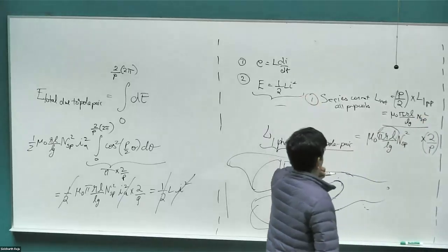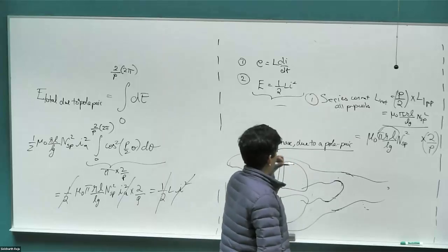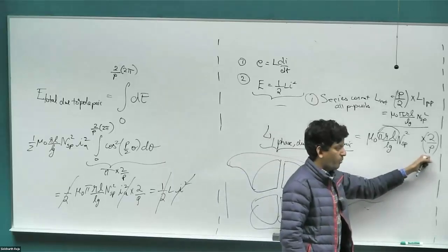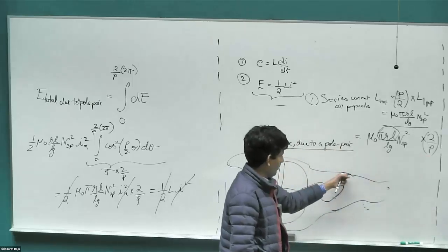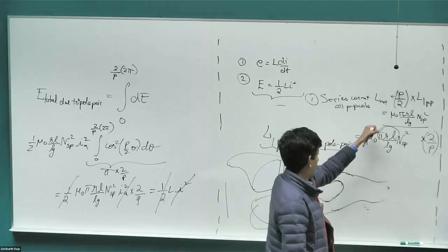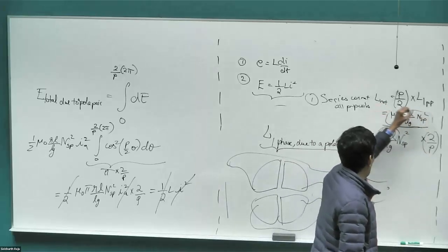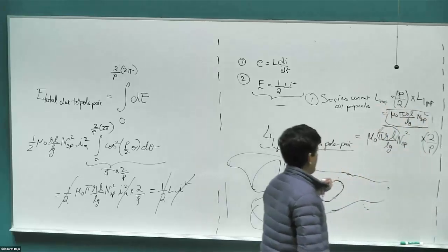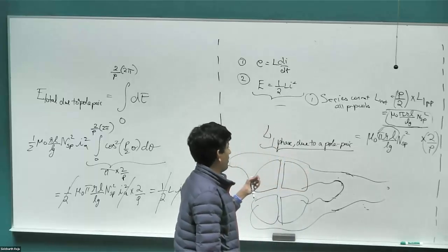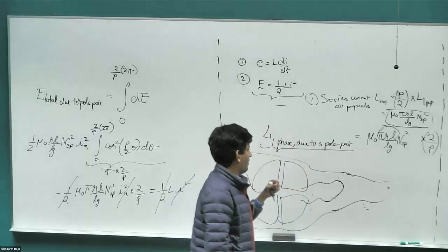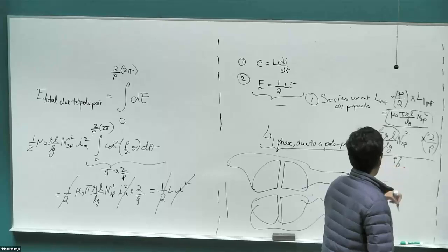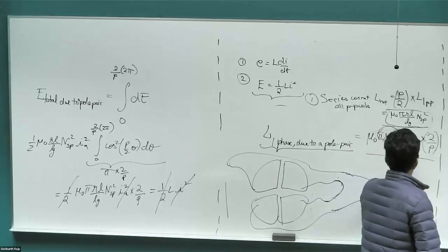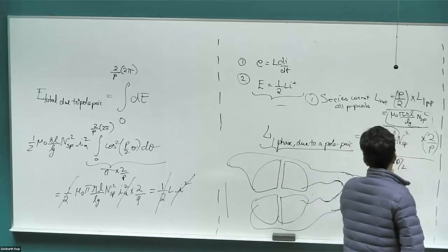So in the textbook, Professor Mohan's derivation is for the case where all the pole pairs are connected in series. All the coils creating the poles are connected in series and you have these windings coming out. So that's why the expression in the textbook would just be this form alone, without the 2 by p factor. But again, there are multiple ways you can connect them. If you were to connect them in parallel, then your inductance would just be divided by a factor of p by 2.